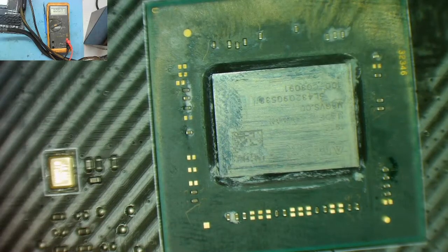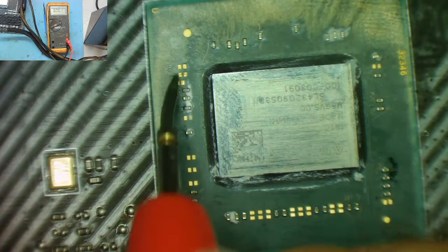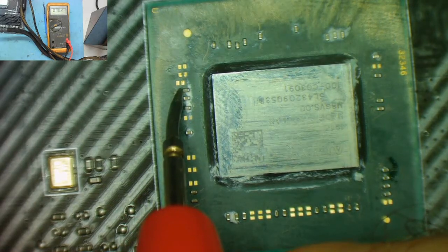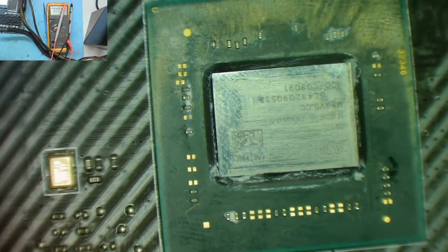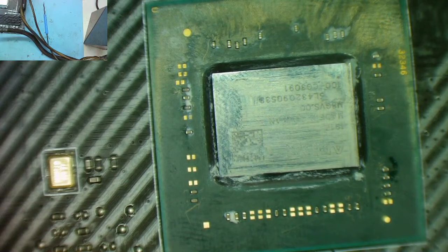Glasses on. There's something there. Top one, I think it was. You've got to be careful when you're doing this not to short to another capacitor as well. 0.7. Well, it's a bit more. Okay, I've got some voltage on the north bridge, as I said, but from my own experience, that doesn't look right to me. Those voltages are very low. But I've never worked on these boards before, this chipset.